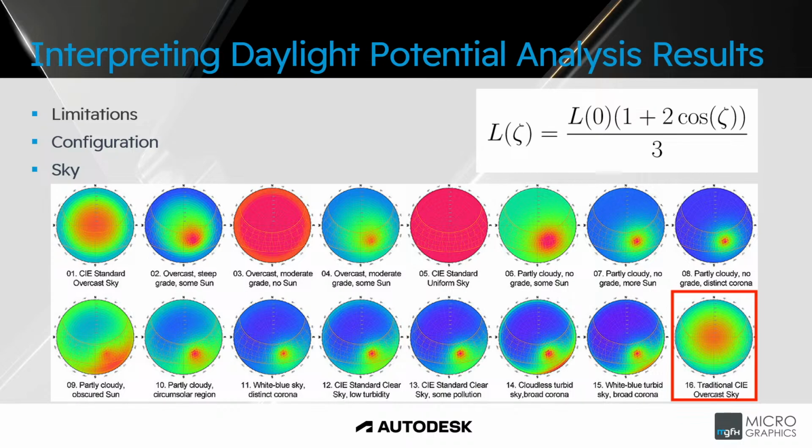Configuration. The daylight analysis is initialized with a set of default configurations. These are set based on Forma's research and external research into standard values used in similar simulations. The sky: the design for daylight factor calculations is based on the CIE overcast sky for the 21st of September at 12 o'clock. The International Commission on Illumination, CIE, in French the Commission Internationale de l'Éclairage, is the international authority on light, illumination, color, and color spaces.